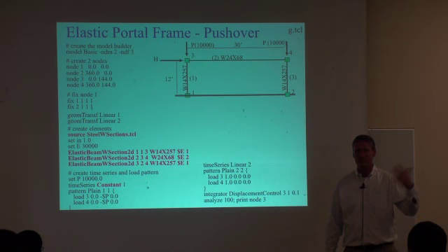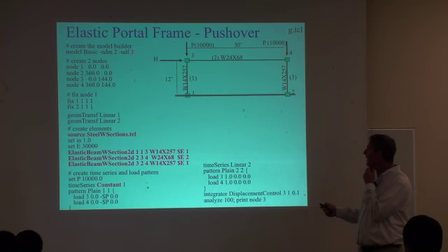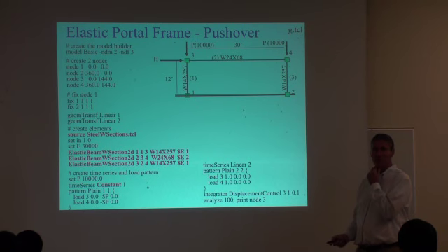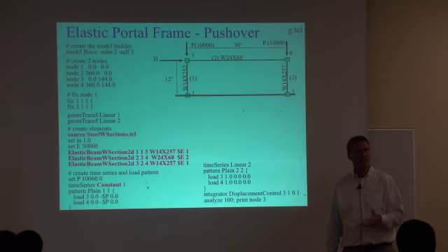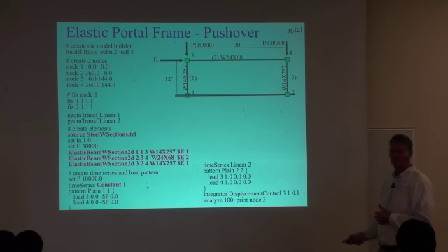I'm doing a couple of different things from the basic approach. So we're creating my model basic, NDF is 4, nodes. I'm fixing nodes 1 and 2. I've got 2 geometric transformations. Linear, they're both linear, 1 and 2. I've also got PLW sections.pickle. This is a file containing the W sections, and the procedures in there. One of these procedures is to create an elastic beam. You give it the tag, the 2 nodes, and the section you want, what E is, and which geometric transformation. Okay?